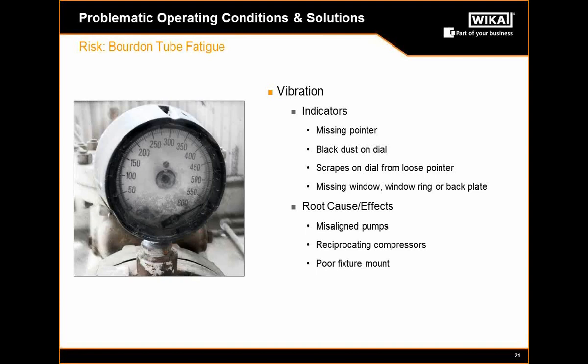As we discussed, just like pulsation, this eventually will break down your movement. The metal wall of the Bourdon tube will fatigue, and it will lead to a release of media in your plant. In order to address this, you want to begin by investigating and finding out where that vibration is. If it's something that can be addressed, such as a cavitating pump, start there. If not, we have options that we can offer to help you fix those problems.